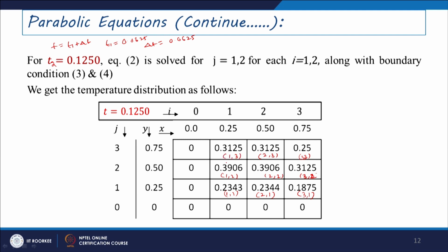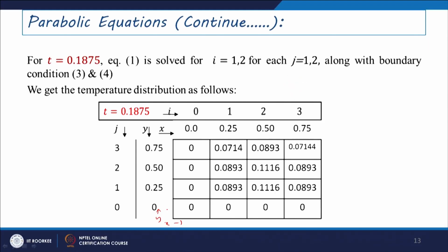All of these values corresponding to the i and j coordinates, you can put and obtain. For further increments of the time step, if you use the x coordinate in this direction and the y coordinate in this direction, and put all these values, we can obtain the temperature at different grid points. Further movement for t, we can also obtain in this form, and this can be tested easily since the calculation proceeds one by one. That is why you can compute and find these values here.